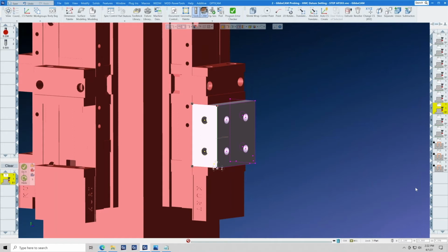What are the real tangible benefits of doing this? Number one, you will increase part quality by letting the probe interact with your program to create more accurate parts and reduce scrap. This works on small as well as large batch processing, even if you're creating one part. Work within your machine's accuracy capability to tighten your output tolerances.